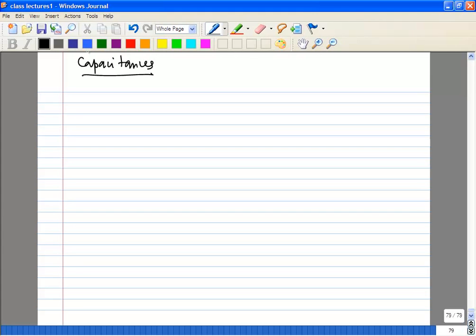At low frequencies, that's good enough. At so-called high frequencies, you need to consider all the appropriate device capacitances. What are high frequencies? Depending on the size and the bias current, the device has what is called a transition frequency. So low and high frequencies are relative to that transition frequency FT. We'll see the expression for FT.